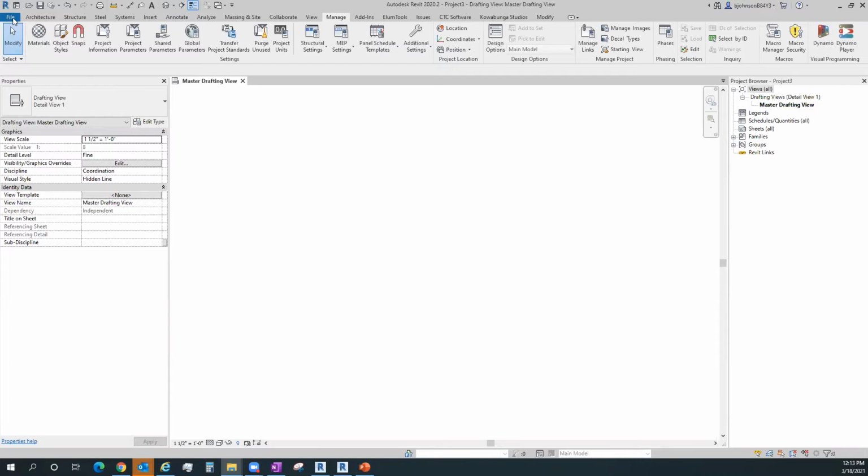But there's a lot of times when those patterns do not transfer. So as you do a couple of them manually, if you have one that has a lot of different fill patterns, I would go through and try to swap those out with something that Revit has. A lot of times you'll have patterns that don't match between Revit and AutoCAD. You may even have to create new patterns from time to time inside of Revit. If you don't want to create new patterns, you could just explode them ahead of time in CAD and then not have to worry about a pattern. It would just be those bazillion little line segments that need to go potentially on a line style that works within Revit at that point.